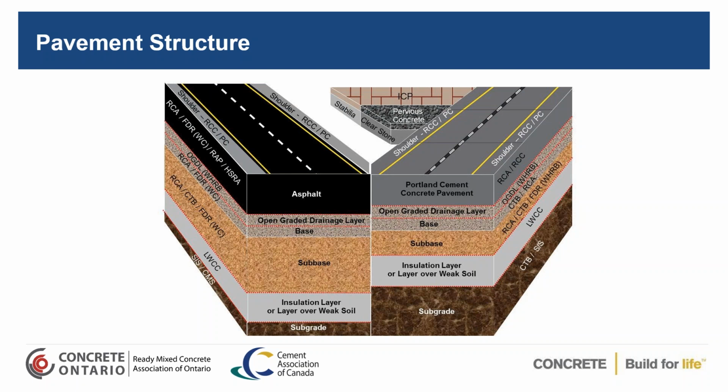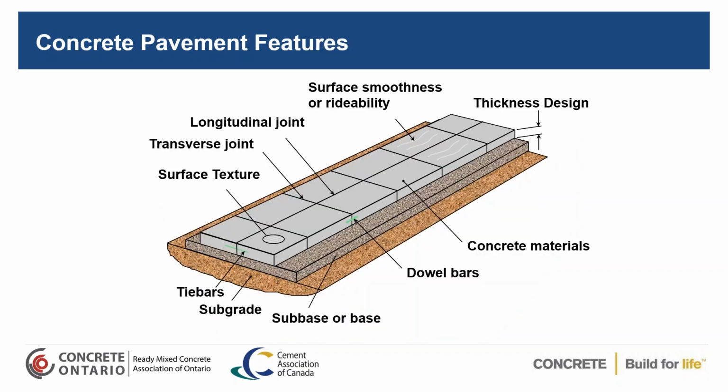The other thing is, because you're getting a really strong friction developing and the concrete itself is gaining strength, you're going to have to get on and cut that concrete quicker. If you don't, the strength of the bond between the open graded drainage layer and the concrete is going to exceed the strength of the concrete, and you'll get some random cracks occurring. So those are just a couple things that you have to take into consideration.